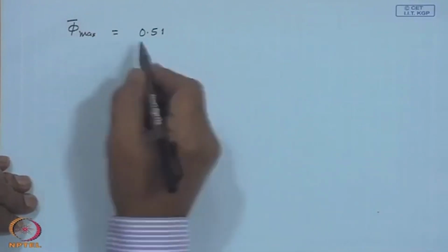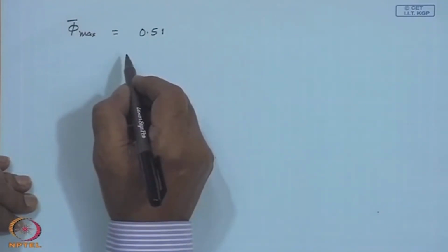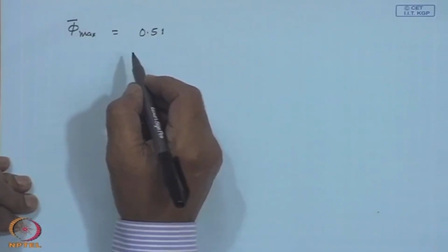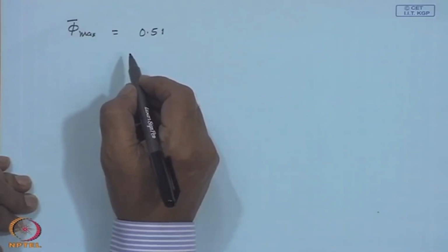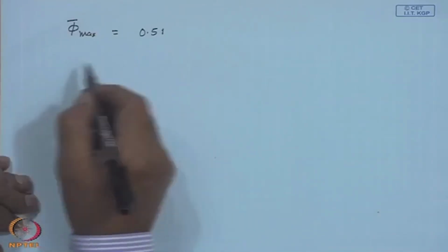Okay. So, once again, first thing is all preliminary: R, R bar, Rn, H0 bar, KT bar, HD bar by H bar, IC and IT noon. Then from that the critical radiation level we have calculated, then the non-dimensional critical level, then the maximum utilizability corresponding to T minimum, based on which we have calculated IC. So, that is the sequence.